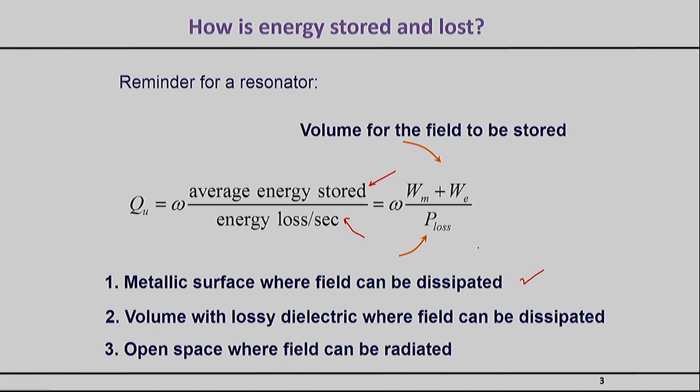Finally, something a little bit forgotten often is radiation. That's particularly of concern when we're talking about high frequency designs. Unfortunately, fields tend to radiate away from the structures that are holding them, and a lot of times, designing for low ohmic loss may actually lead to high radiation. For example, wide transmission lines tend to have lower losses than narrow transmission lines, while wide lines also tend to radiate fields more than narrow transmission lines, and so those three may actually compete with one another, depending, of course, on what your frequency range might be.